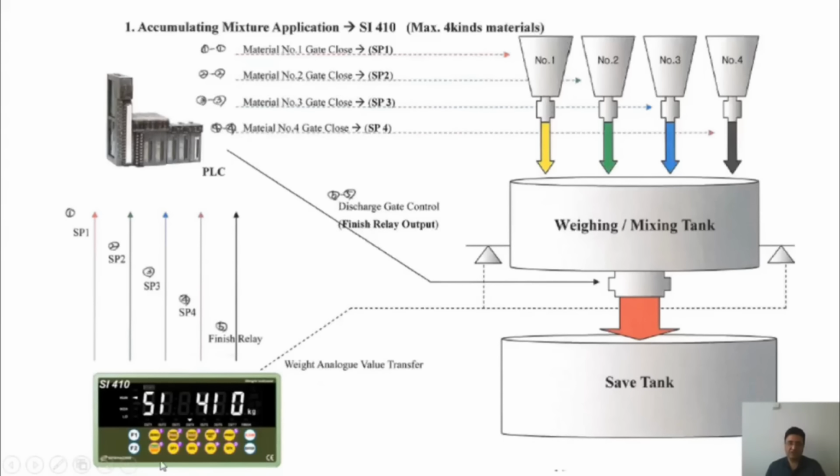The role of this display here is that we can monitor the weight, and in addition, it has high resolution. If we wanted to connect the load cell directly to the PLC and use the load cell card here, it wouldn't give us the necessary and sufficient accuracy. Whereas when we use the weight display, because these displays have high resolution, they provide us with greater accuracy. How we can connect a weight display to a PLC, we will definitely talk about in future lessons as well.